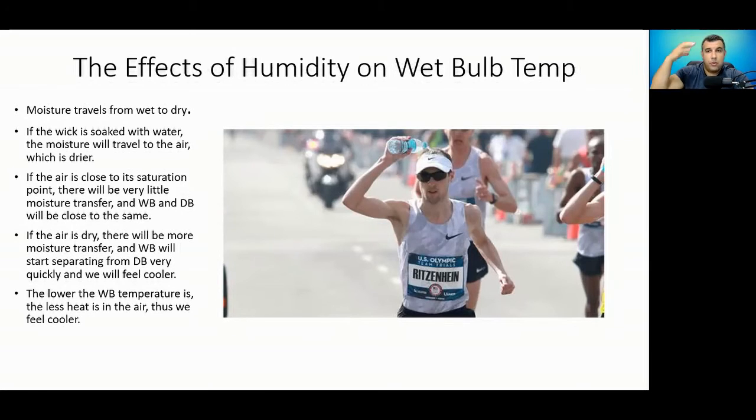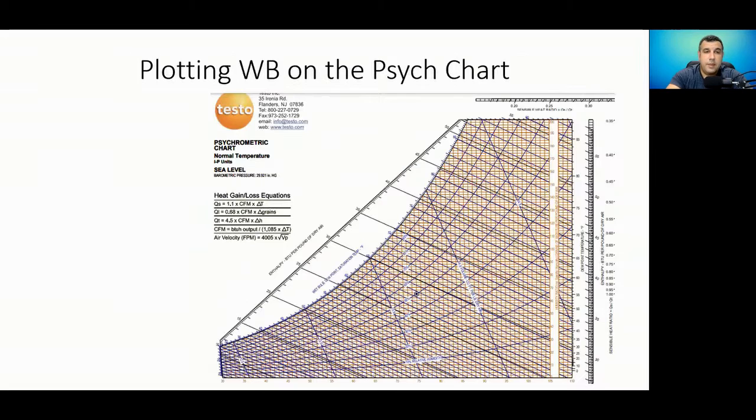And as that water evaporates back into the air around him, that evaporative cooling process cools him down. Now, if it's a very humid day, there's not going to be as much evaporative cooling, and so he's not going to feel as cool. But if it's a drier day, there's going to be a lot of evaporative cooling that takes place because the outdoor wet bulb temperature is a lot lower, and he's going to feel very cool and refreshed after doing that.